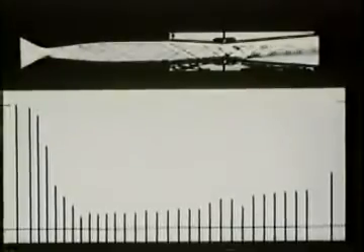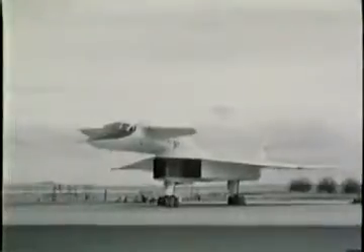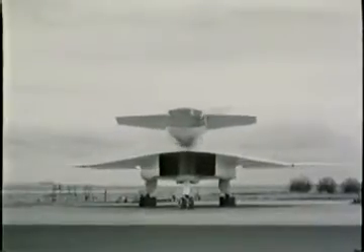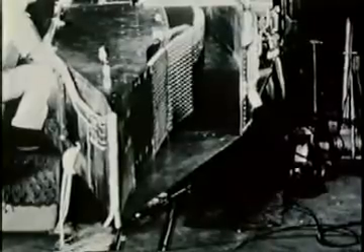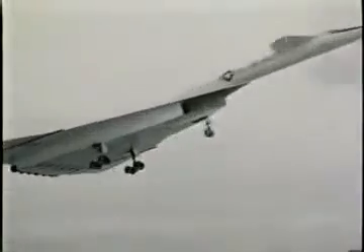Here we are looking down the throat, so to speak, of an engine inlet designed to operate at Mach numbers up to 3. This wind tunnel model of the same inlet duct has the top plate removed to show the means provided for varying the geometry in order to improve the pressure recovery. Since the supersonic flow is provided by the relative motion, the inlet duct corresponds to our second throat. However, the idea of a fictitious first throat is still useful for understanding the behavior of the airflow.